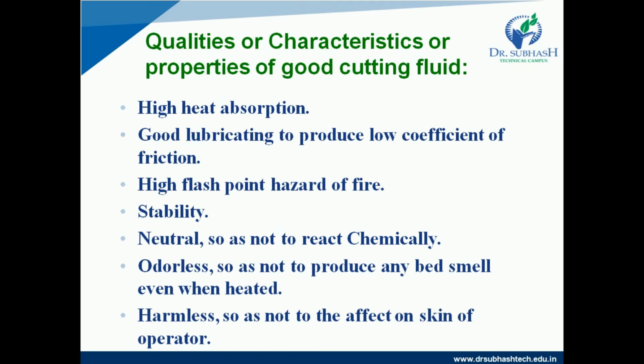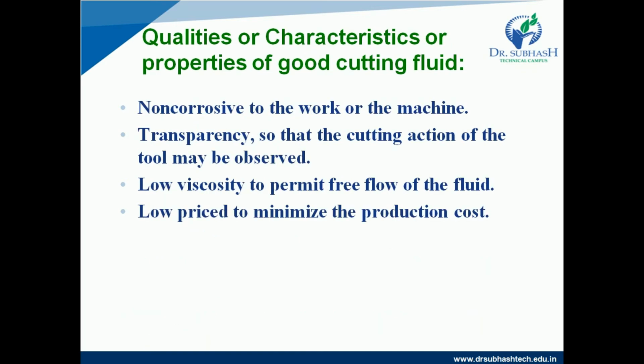It is non-corrosive. Transparency is also there. So with the use of that, we can easily see the operation, so that the cutting action of the tool may be observed. Low viscosity is also there, so it allows free flow of the fluid.